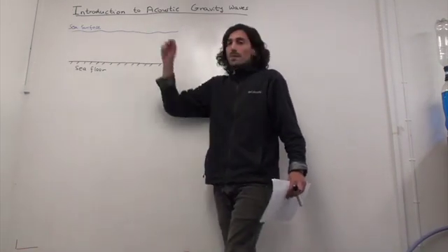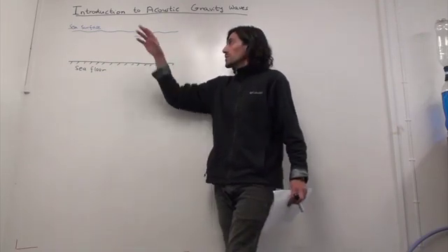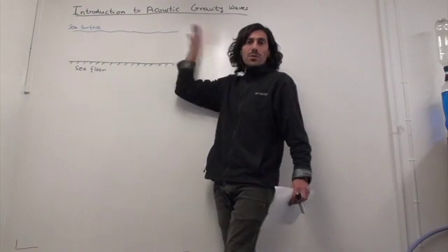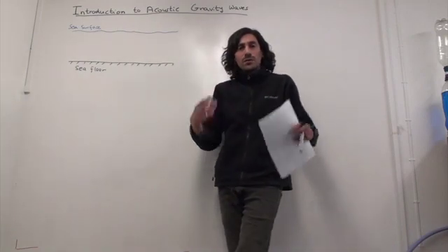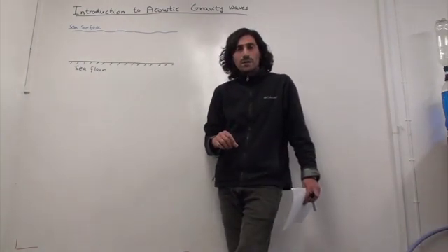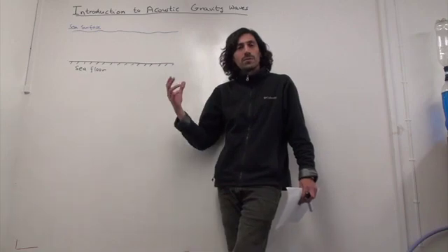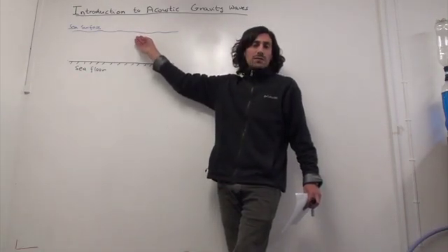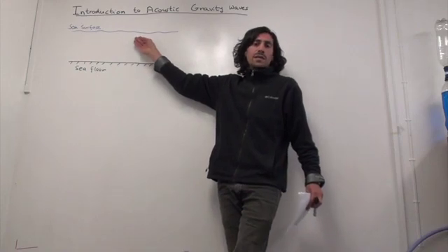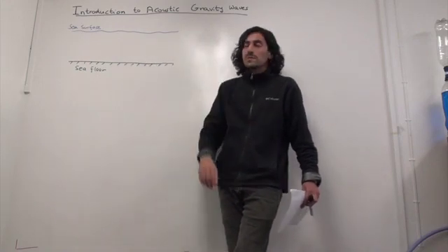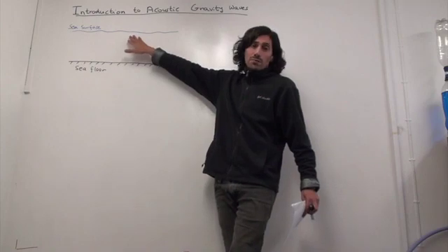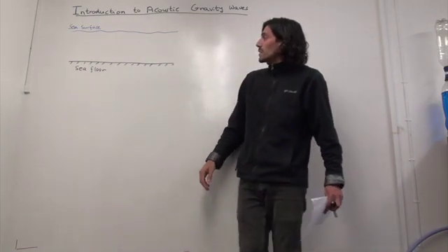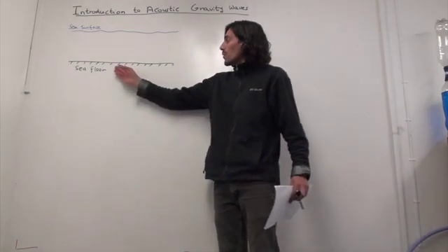Wind is generating them, for example, it can be other sources. Wind is generating them, so the inertia wants to move them, but gravity wants to restore them, right? And that's why we also call them gravity waves. So these are surface gravity waves, because the effects of gravity are very important in the dynamics of these waves. You can't ignore gravity here, definitely not. This is the seafloor.